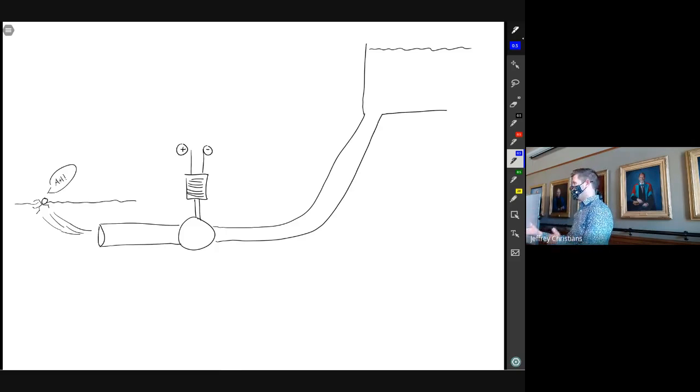We're using energy in the water to do something. The water starts with potential energy, and then we take some of that out and we use it and turn it into electricity. At any point along the system, the energy that we can use is the mechanical energy of the water. We can't use the thermal energy of the water, so that's what we call losses.